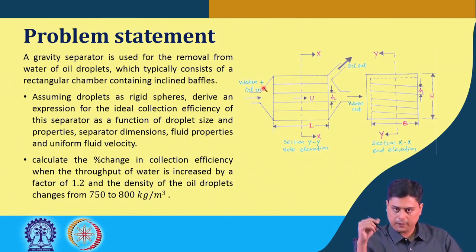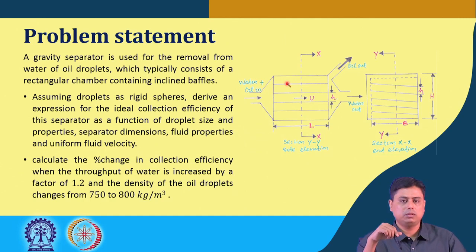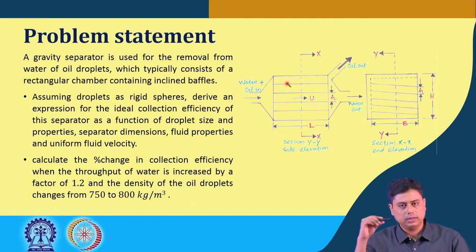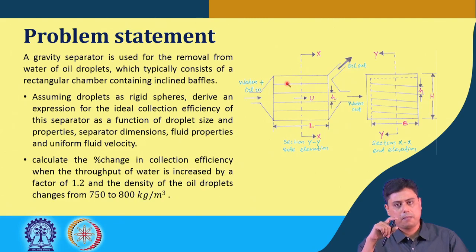Now, you understand that when it flows here, the time it takes to rise to the under surface of the baffle depends on the concept of terminal velocity, and the time it takes to go with the water, because here we have assumed, let us assume, that there is a uniform flow, the fluid velocity.